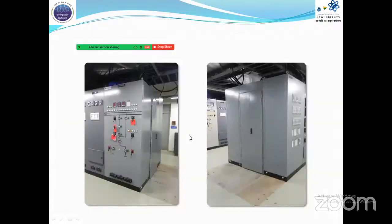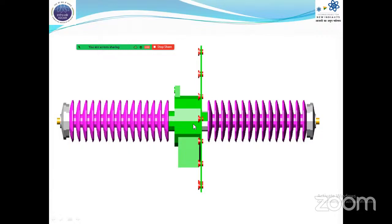Because the CTs are shifted here, the CT sizing mainly depends upon the knee point voltage of the CT, and that affects the weight of the CT. So to minimize the weight and to make this system simple and easy to install at higher elevation, we have to restrict the knee point voltage of the CTs. To minimize the knee point voltage of the CTs, the lead resistance has to be minimized.